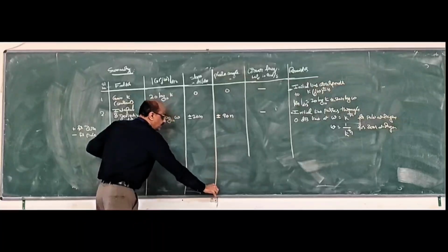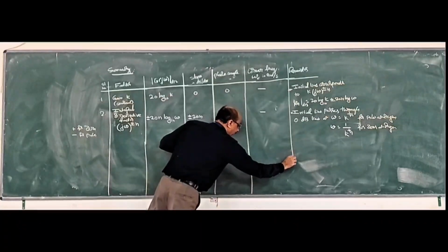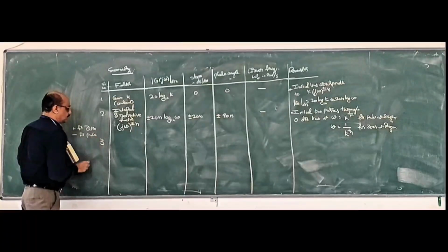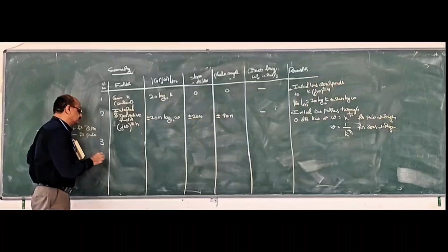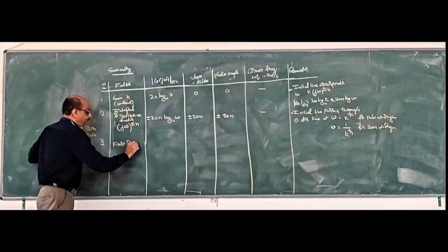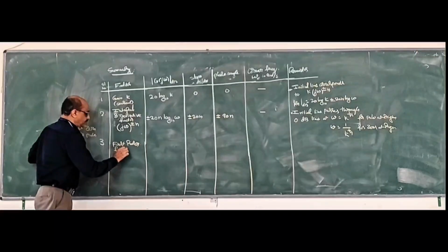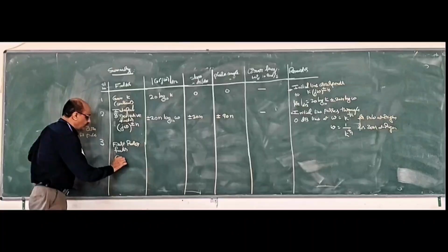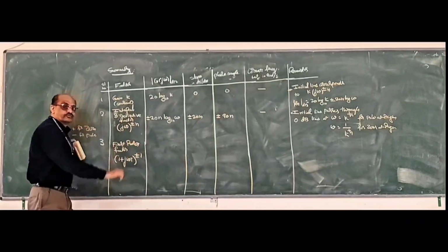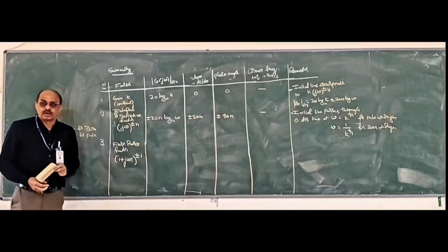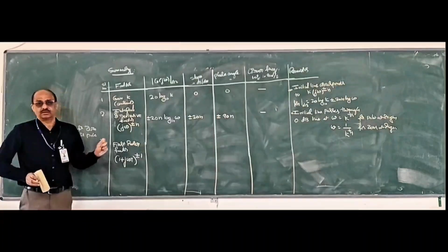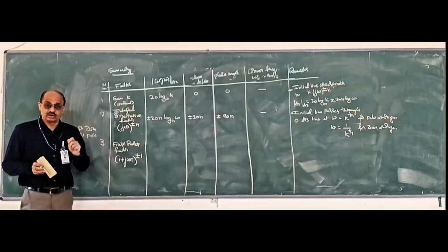Let me now go for the first order factor. A first order factor can be written as 1 plus j omega t, plus or minus: 1 plus for a first order zero, minus for a first order pole, again plus 1 always.